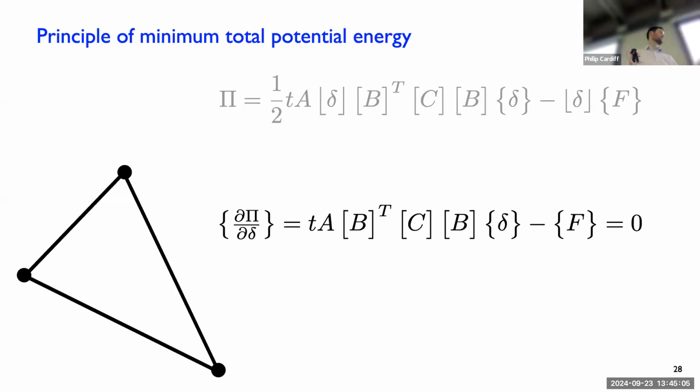Conceptually, you'd have to write out all the components to actually check that this makes sense. But in the f delta term here, you can see the delta drops. The half delta squared just becomes a delta on its own, and then we're left with B, C, D. So this is a general definition of our stiffness matrix. This thing here is our stiffness matrix times our unknown nodal displacements, minus the applied external forces.